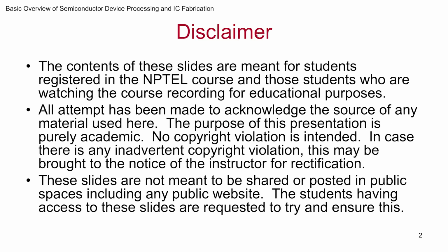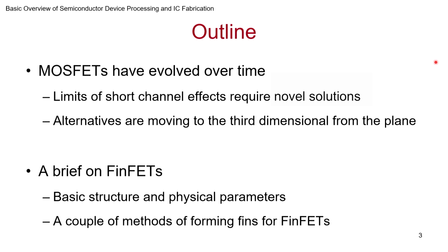First, the disclaimer. This is going to be the outline of my talk. It's broadly divided into two parts. First, I would say how MOSFETs have evolved over time, and a very brief tutorial on why we need to do that. What is the short channel effect that we are trying to overcome that requires novel solutions, and the alternates that we are moving towards. You will get an idea. The basic idea seems to be that we had devices which are flat, source and drain were flat and on the surface of the wafer, but slowly they are starting to move into the third dimension, that is in the vertical dimension from the plane. A little bit of that.